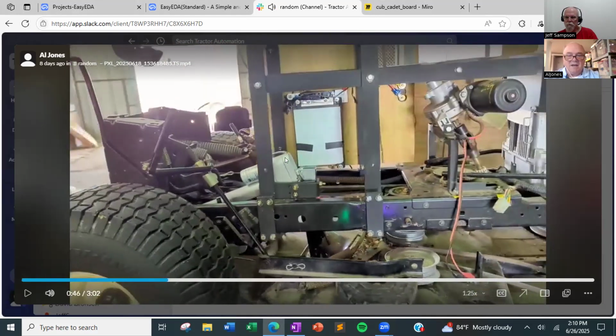So this is the back side. Here's the linear actuator connected to the hydrostatic transmission that's connecting these two wheels. I was just trying to see if this physical connection was going to work for me. The short story is I think it's going to. I think I'm getting a good inch in reverse and a good inch going forward, and this linear actuator is able to provide enough oomph to pull against that hydrostatic transmission control arm.